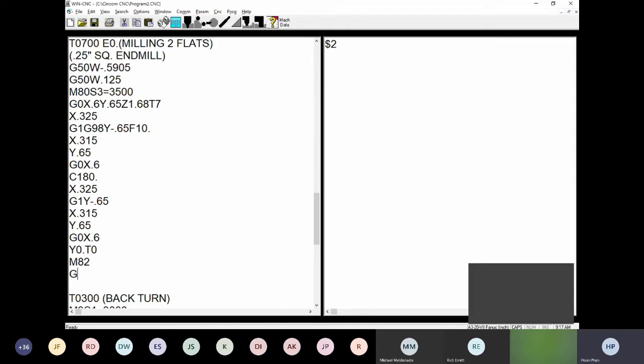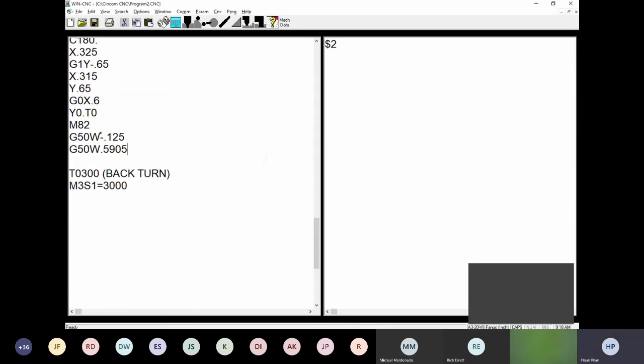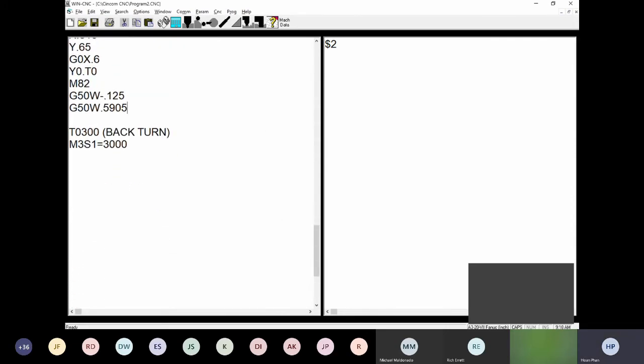So after we're done, remember we have to cancel it. All right, good job, Jerry. W, so we just cancel it for whatever we have here. G50 W 0.5905. Everything back to normal. Okay, good.